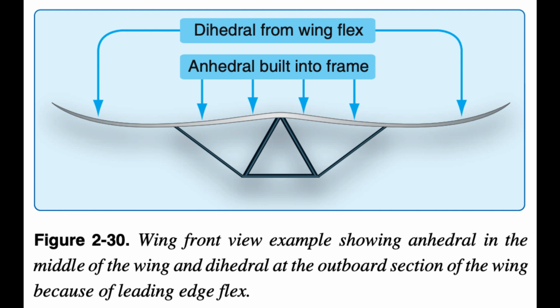WSC wing rolls is to examine the carriage and the wing moment from the carriage point of view. For example, the CG hangs far below a wing weighing 1/8 of the carriage weight. When the control bar is moved to the side, creating a moment about the carriage/wing hang point, the carriage stays vertical and the wing rotates around the carriage. Therefore, there are two rolling moments that both contribute to the WSC rolling into a bank.